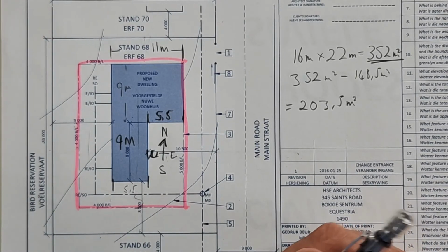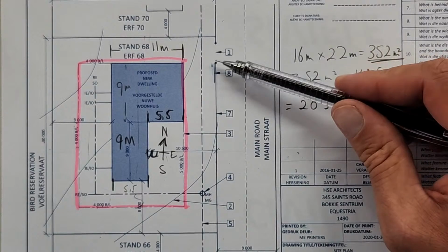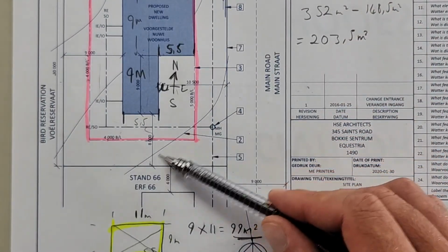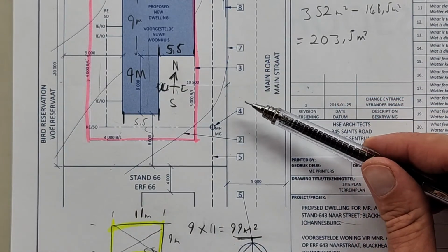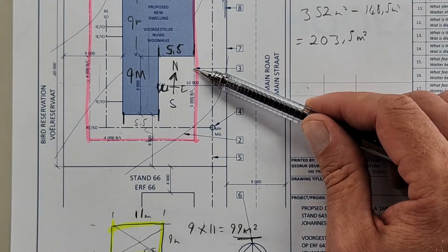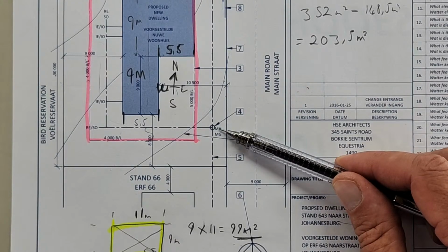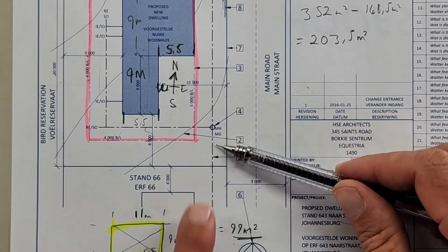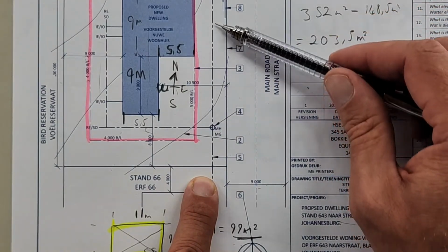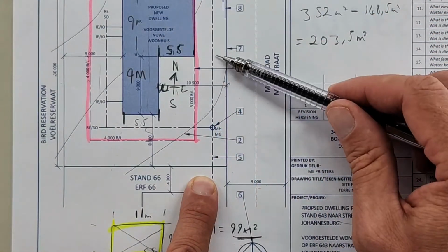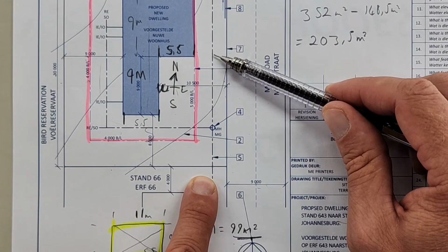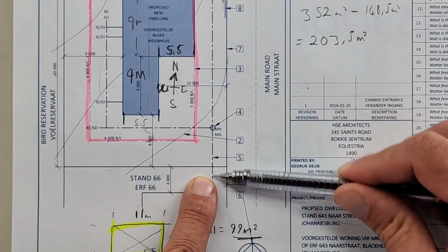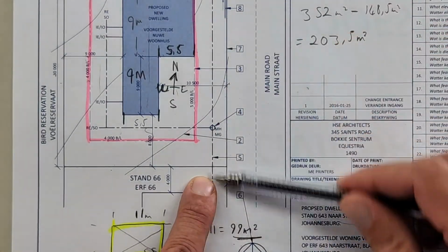Okay, what does feature 1 represent? We'll be quick. That's the entrance. Okay, feature 2 here, that is, I said contour lines, contourlijne. Number 3 is ons boulyn, building line. Number 4 is the manhole, mangat. Number 5 is your municipality wheel, municipal sewer. Quick question, what color is a municipal sewer or any other sewer lines on here? Brown. Anybody knows why they chose brown? I'm not sure, but at least I can remember why. Or I won't forget that one. Okay? Municipal sewer is brown.